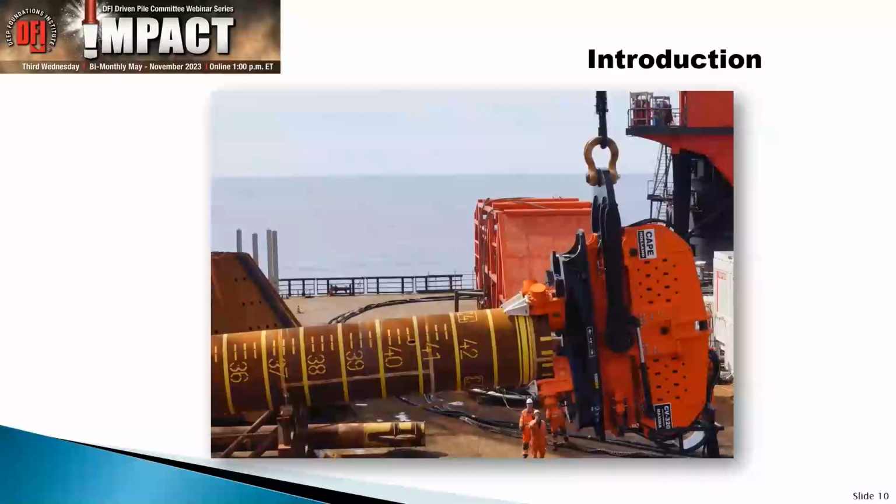Here's another example. This was for an offshore job where you see a pile about 42 meters long. You see the people there in the orange suits at the bottom, center of the picture, and you see the size of the vibratory hammer. Vibratory hammers are getting bigger and bigger and allow you to drive larger and larger diameter piles.